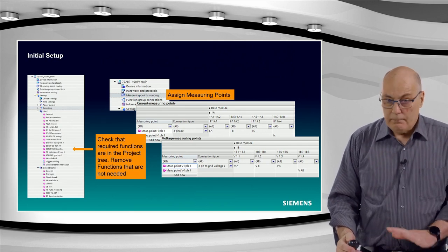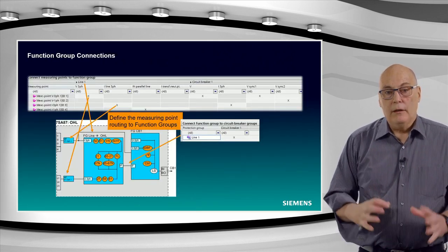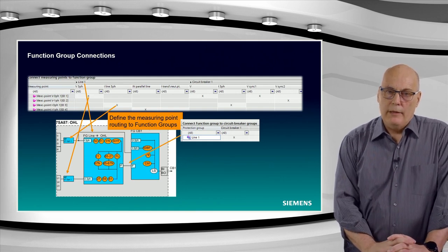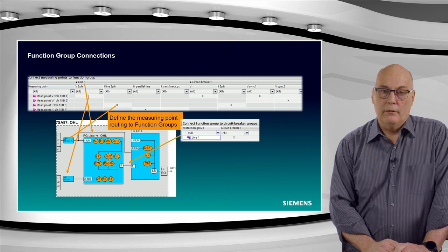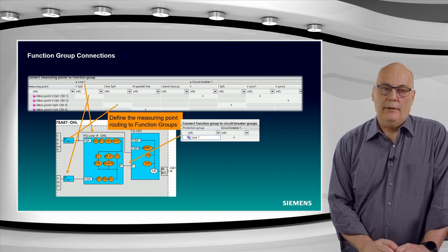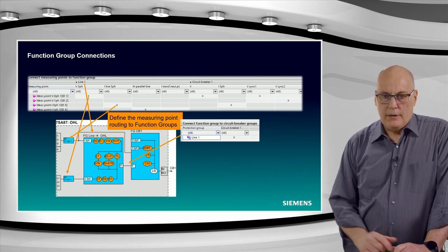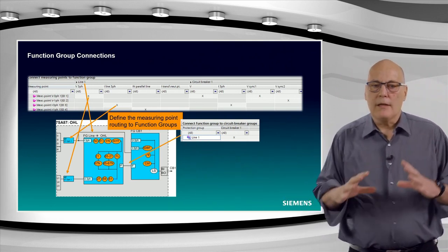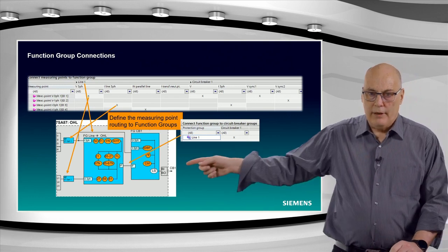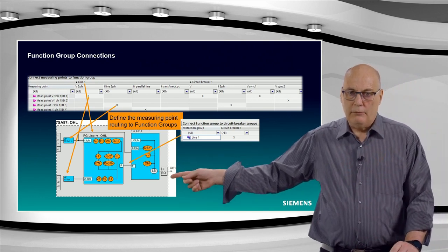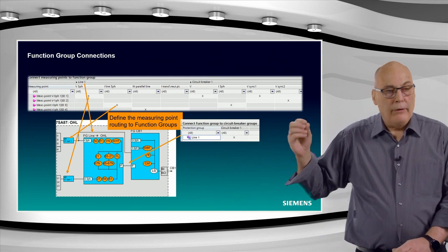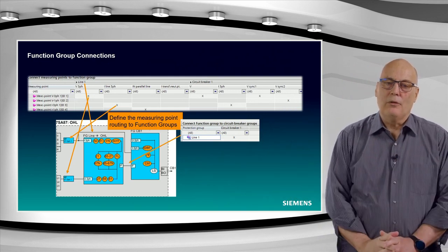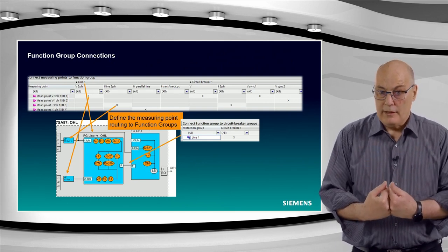All right, that is, I think, the DIGSI configuration as you would do it. This is a graphic representation, maybe easier to explain, to re-emphasize what we just looked at in how you do it in DIGSI, just a picture of that. At the bottom, you see this diagram, and you can imagine that the outer gray block is a physical device, and the physical device would have terminals to the outside. Here you can see binary inputs and outputs, for the trip signal to the breaker, maybe the close signal to the breaker, feedbacks for breaker auxiliary status, and so on.